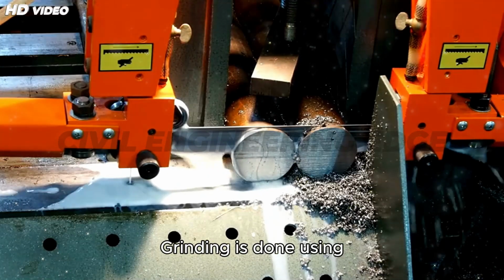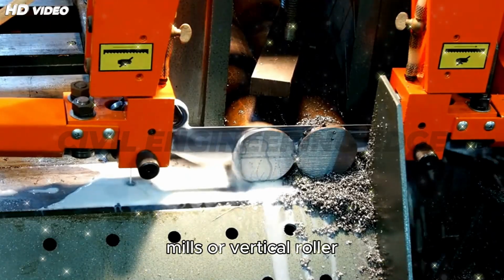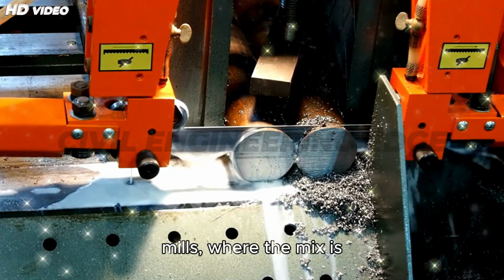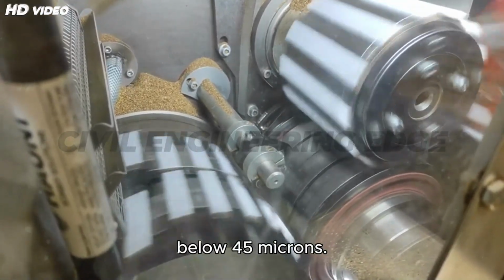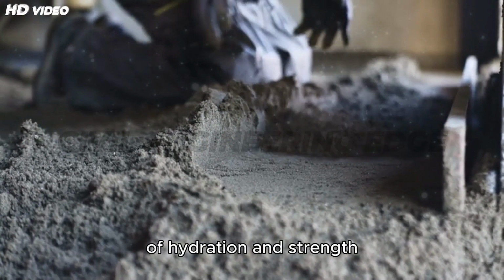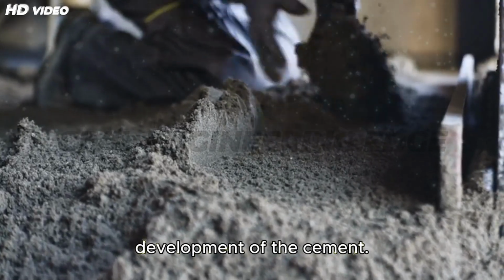Grinding is done using closed circuit ball mills or vertical roller mills, where the mix is ground into a powder with a particle size below 45 microns. The fineness affects the rate of hydration and strength development of the cement.